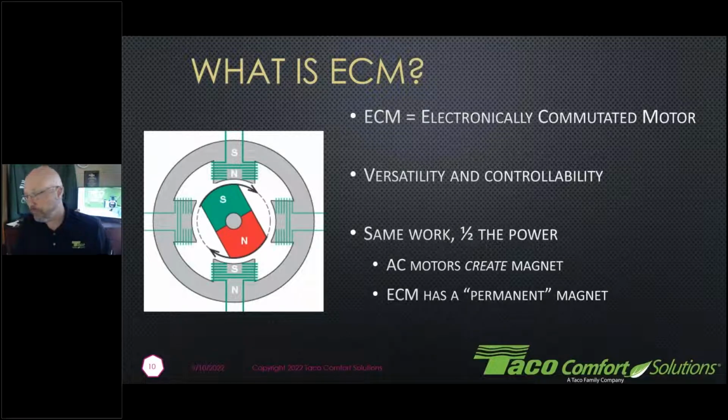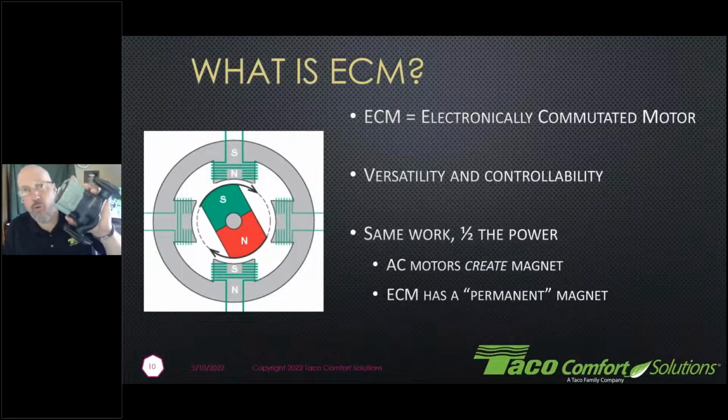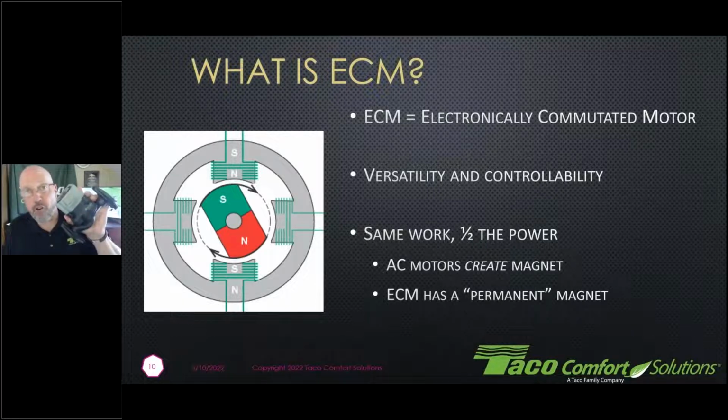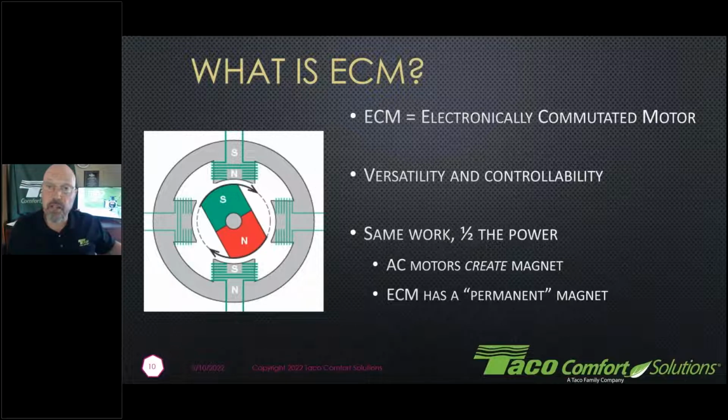our circulator turn. So right out of the box, this circulator maximum power draw is looking at 44 watts. The standard AC equivalent, our PSC equivalent 007, is pulling 80 watts. So we're just about half the power running full speed. Now these all become variable speed depending upon our applications, and we're going to run a lot slower speed to match the demands of the system itself.